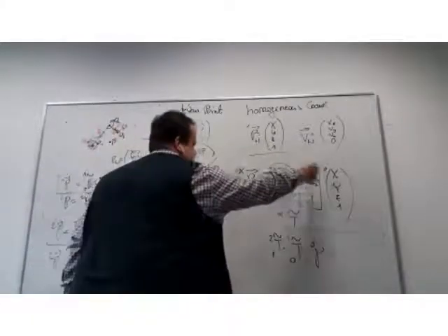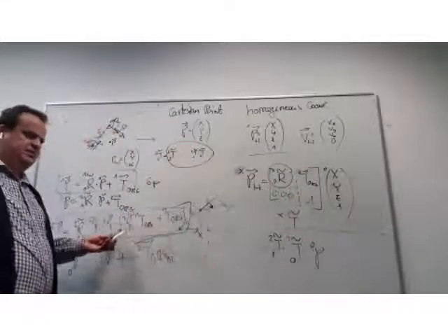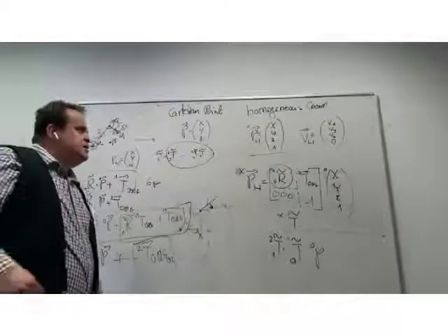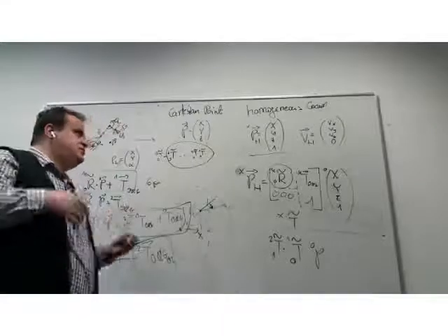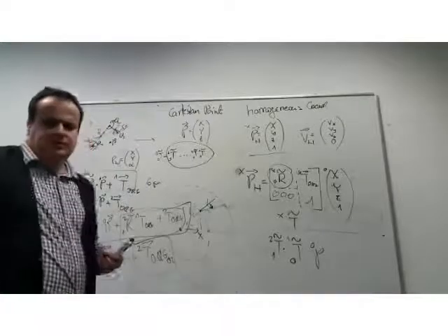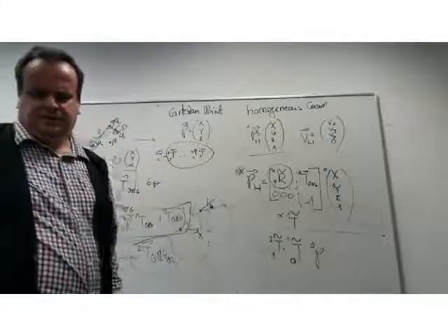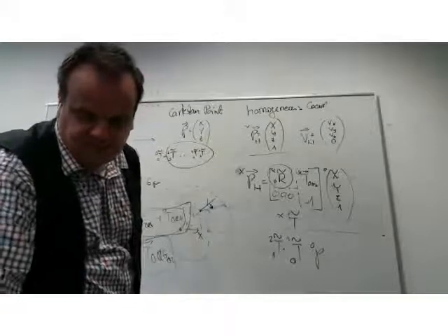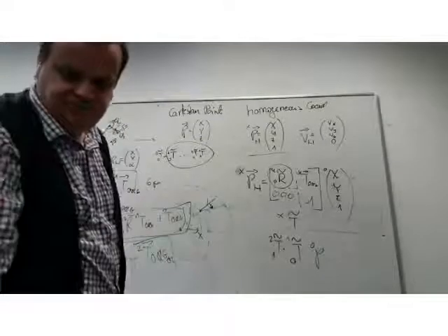And the corresponding translation vector will also be propagated exactly the way I've done here. So switching from Cartesian representation to homogeneous representation allows us to define the position of the robot by multiplying with a matrix.